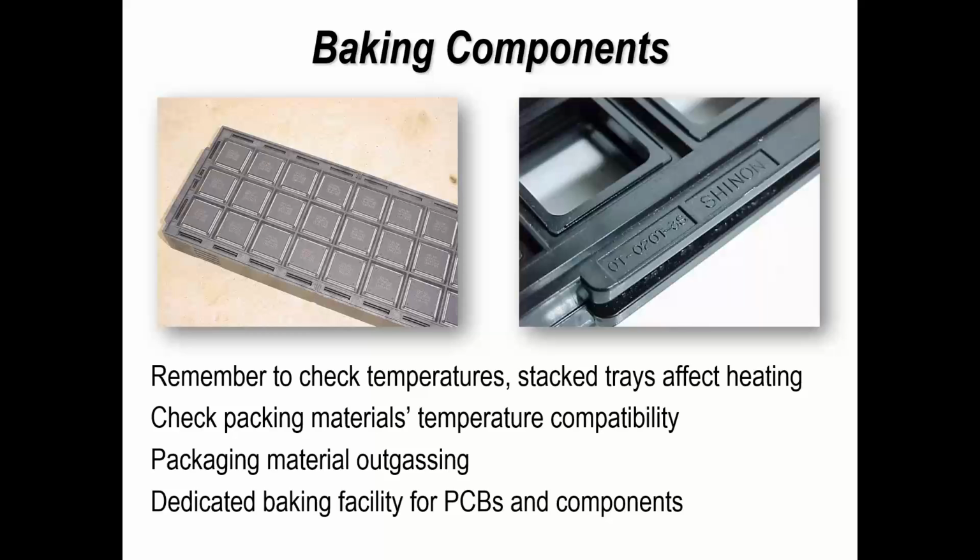And also one of the other things I always say, if you're going to bake a part or bake a board, then you use a dedicated oven. You don't use something you're using for glue curing as well, because potentially the gaseous residues that are driven off during the curing of adhesive and epoxy compounds may cause you solderability and wettability issues on boards or components.